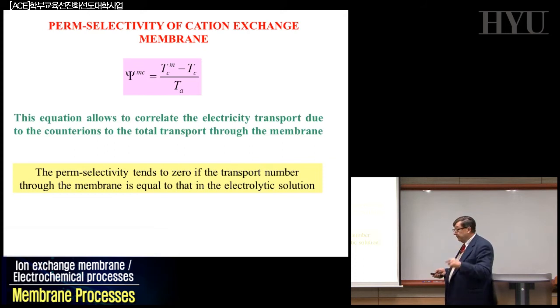That's one point. The other one: remember that, as in all membrane operations, we have fouling phenomena in this system. The mechanism of the fouling in this case is different. It's not just blocking the membrane, etc. That can also happen, but that's not the worst. What can happen is that some ions present in the solution can be attracted, for example, by the fixed charge in the membranes, so they will neutralize the charge density. That happens particularly in anionic membranes. Cationic membranes are easier to handle. This kind of fouling, you don't know how to control.